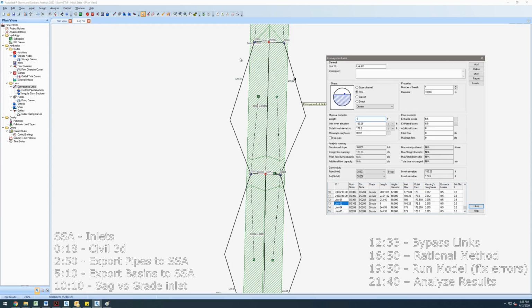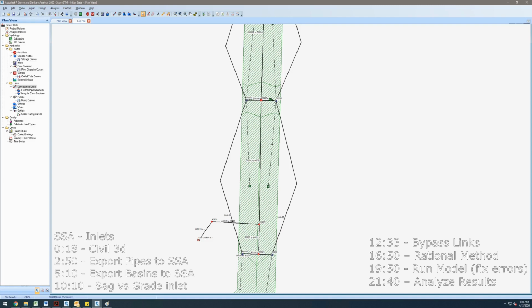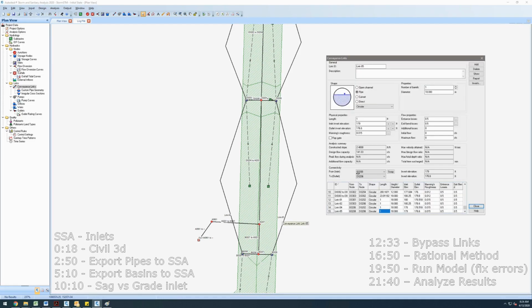So basically, it's going to travel from here to here extremely quickly, and show up here right away, which is really what I want to do. So I'm going to do that for all these. You can see I have link. You can actually just type them in here: 1, 1, 1. I believe I only have those 4 links. And so any water that bypasses here is going to basically immediately make it here, because it's not going to take very far to travel 1 foot. Now, if I had it at 213 foot, there might be a little bit of lag before it makes it to this pipe, which I don't really want to model. I want to model a worst case scenario.